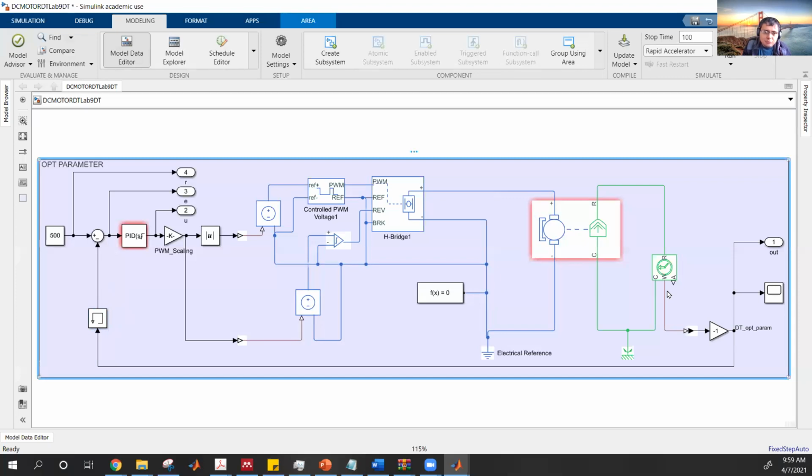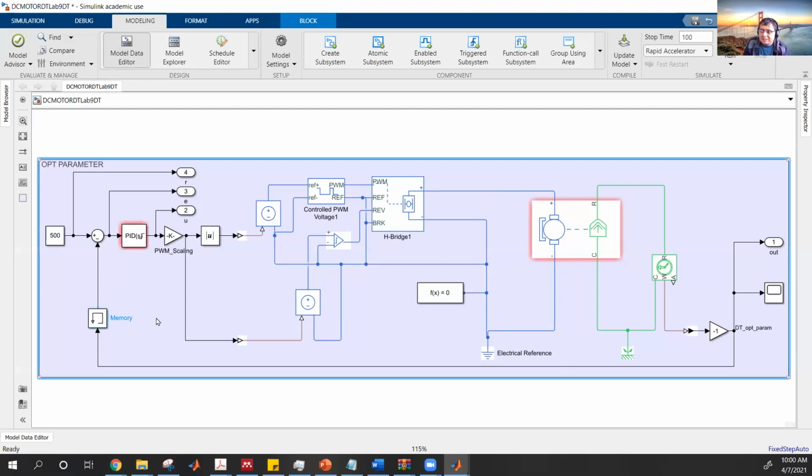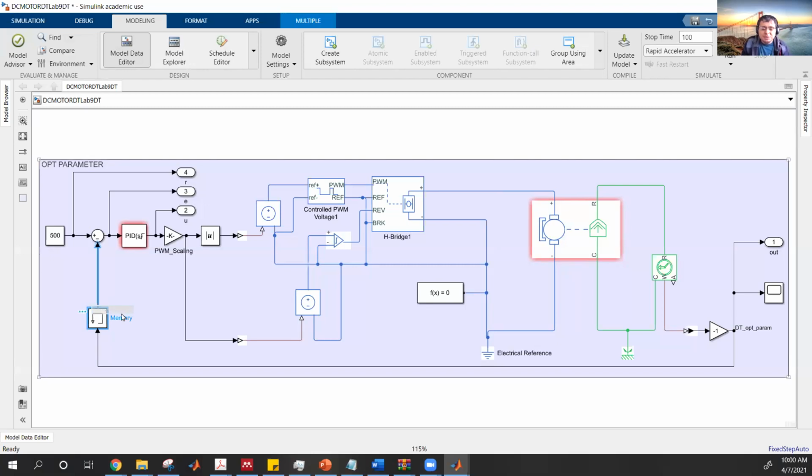So for any feedback loop in your control loops, when you are developing your digital twin, and specifically once you are getting ready for web deployment, you have to include this Memory block just to make the solver able to solve your system. This could look pretty strange at this moment, but trust me, that gave us a lot of headaches in the past. So keep that in mind.